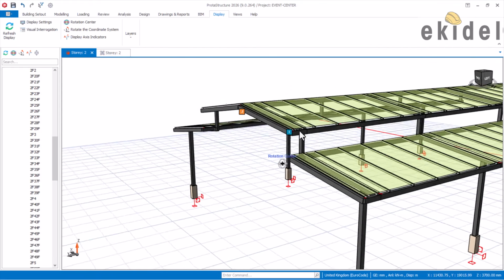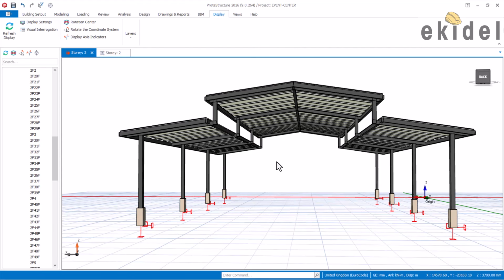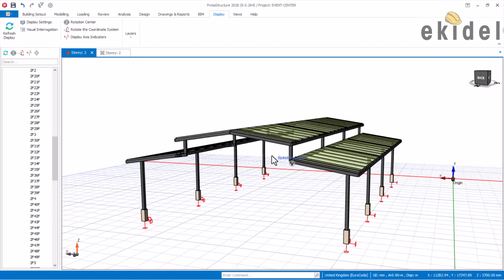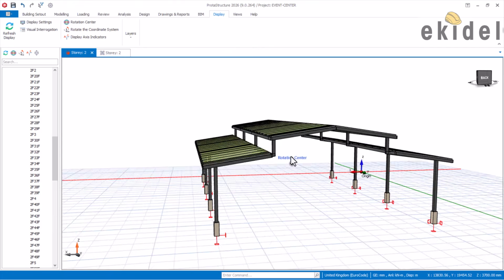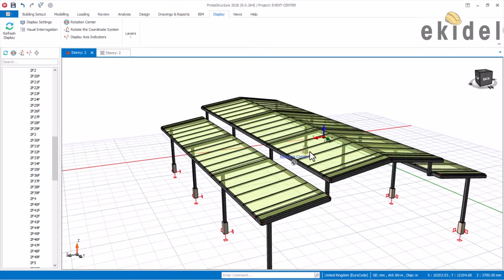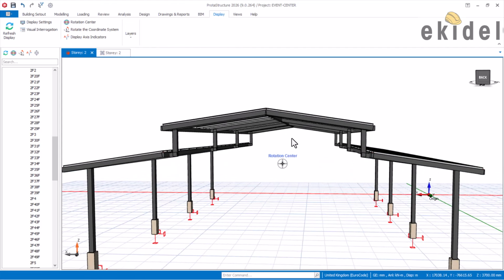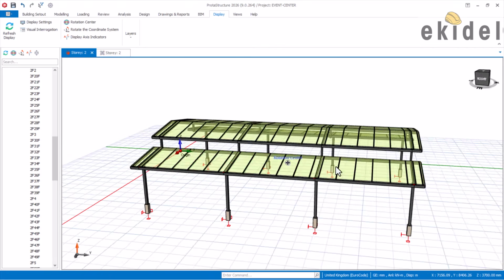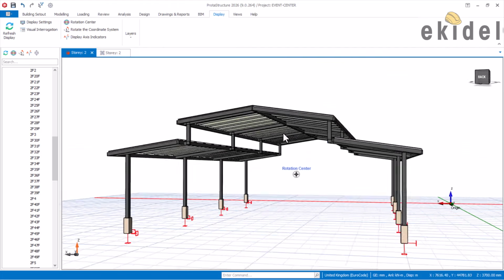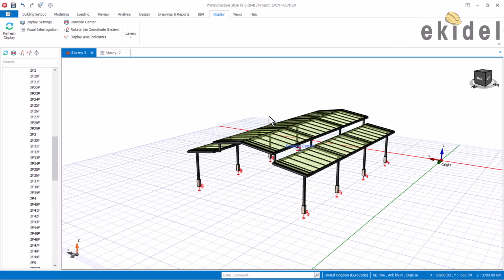For a steel structure, one thing that governs is the wind load. Wind load governs a lot when it comes to steel structures, because it is a lateral load, and steel structures are quite exposed to lateral load, since most steel structures, for example portal frames, are always open structures, which are prone to wind effect. So I'll be showing you how to apply that, and if there is going to be side bracing and also wind bracing, we are going to know if there is need for wind bracing or side bracing that will control the wind effect and keep the building stable. That's fine. So see you in the next video.